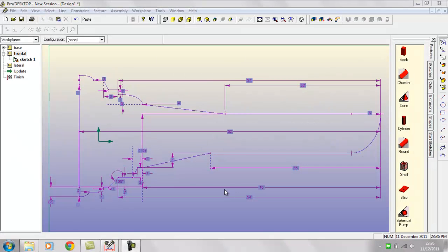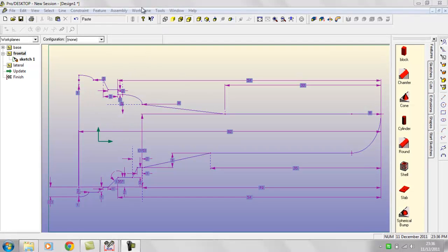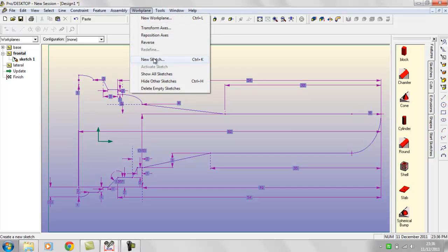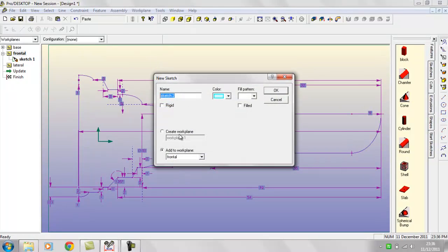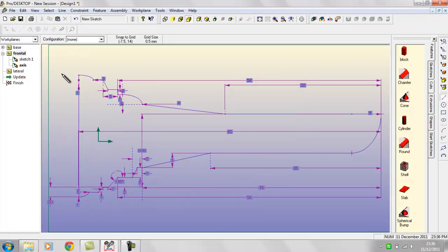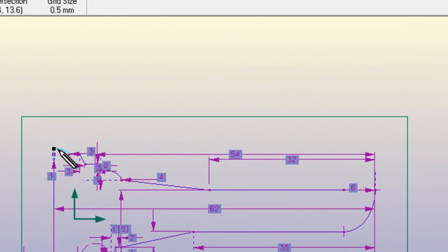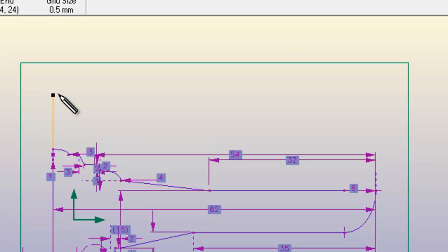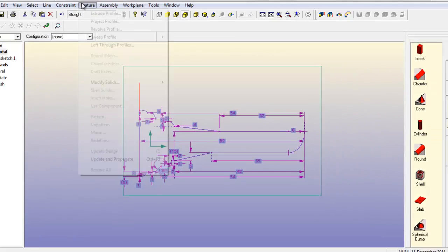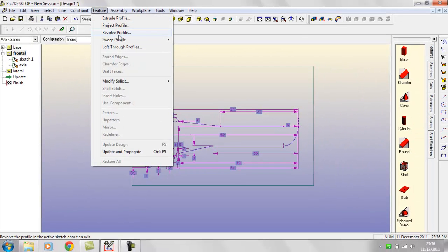Okay, so first we're going to have a look at a wee example of some CAD commands. Here we're looking at the saucer of the Enterprise, and we're going to do a revolution to get the shape. First I've created a sketch for an axis, and I'm now going to draw the axis. There we go. So that's the axis that we're going to use to revolve the profile that we've already got drawn there.